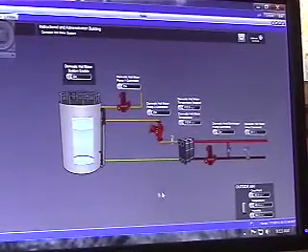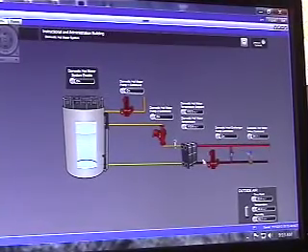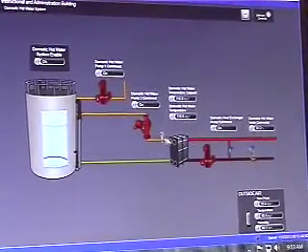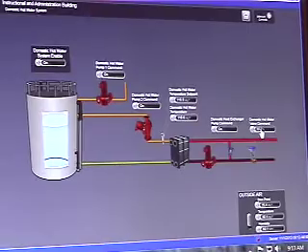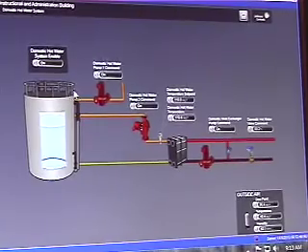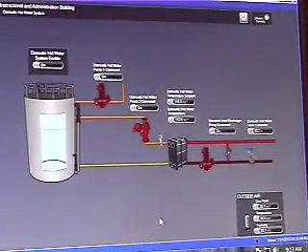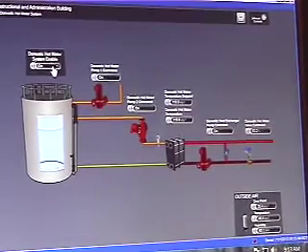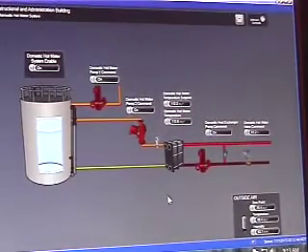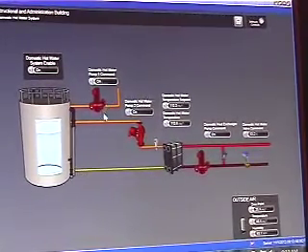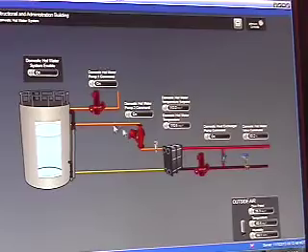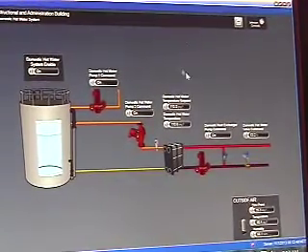Whenever the system runs, we enable the pumps. Here you're pulling from the heat exchanger, and you have a hot water valve here that modulates to maintain 110 degrees going into that tank. So this valve right here modulates open and close to maintain this temperature. This then dumps it into the tank, and then your recirc pump circulates throughout the building. You do have the ability to disable the whole system right here. Just right click, hit off, and it'll disable the system from running. But other than that, real basic setup. All these pumps will run together because this is what pulls it through the heat exchanger. This is what pumps it into the tank, and this is your recirc pump out to the building.